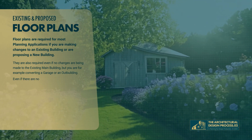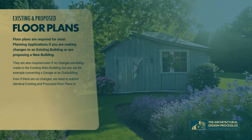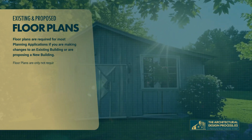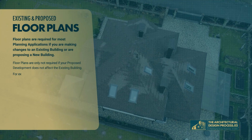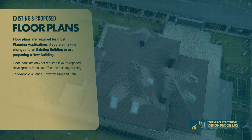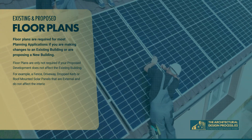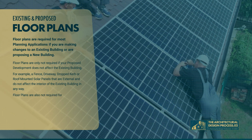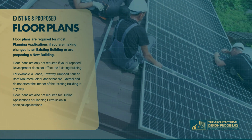Even if there are no changes, we need to submit identical existing and proposed floor plans to show the council there are no changes. Floor plans are only not required if your proposed development does not affect the existing building. For example, a fence, driveway, dropped curb or roof-mounted solar panels that are external and do not affect the interior of the existing building in any way. Floor plans are also not required for outline applications or planning permission in principal applications.